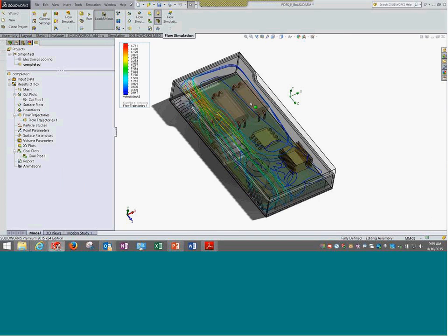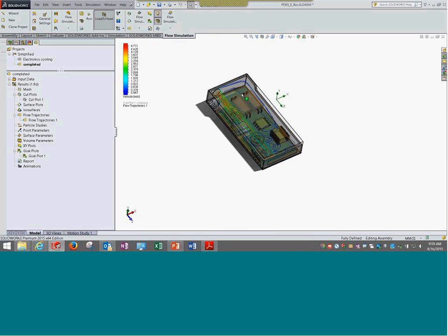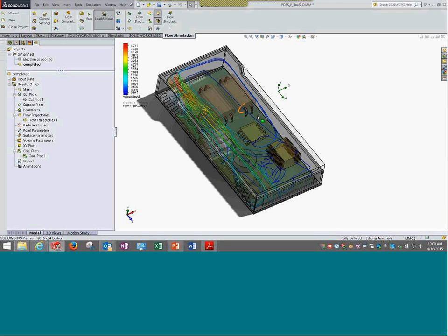What I want to do is prefer having a fan somewhere here, or probably here. I think it can be better here, right? It can directly blow the air on the heat sink. But the problem is, if you blow the air on the heat sink, the air can get heated, and heated air can go all around the system, which is also meaningless. So better, as soon as the air takes the heat, it should go out of the system. And I believe a flow in this direction would be more efficient than anything else.